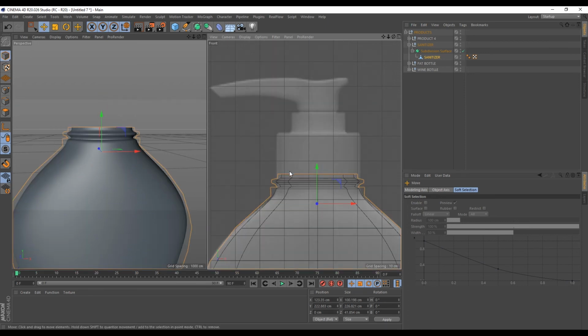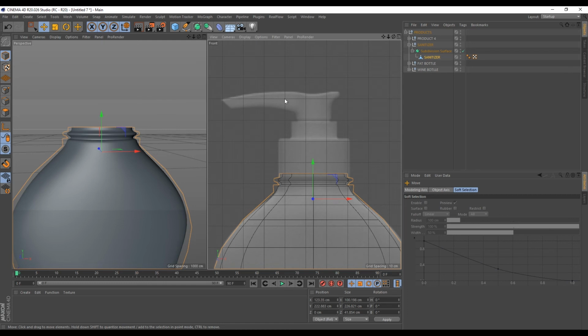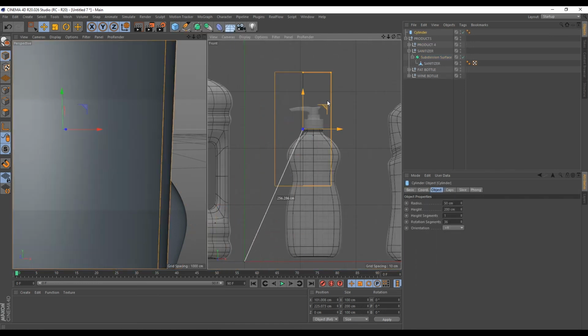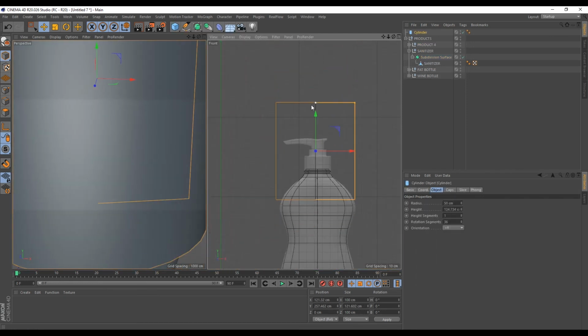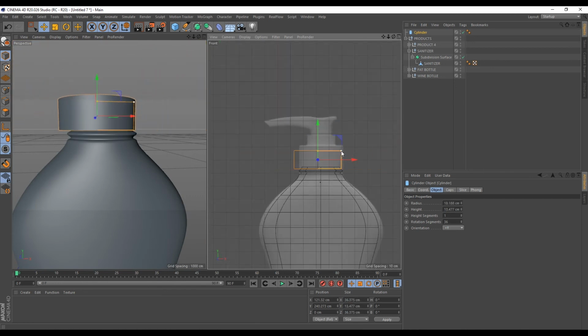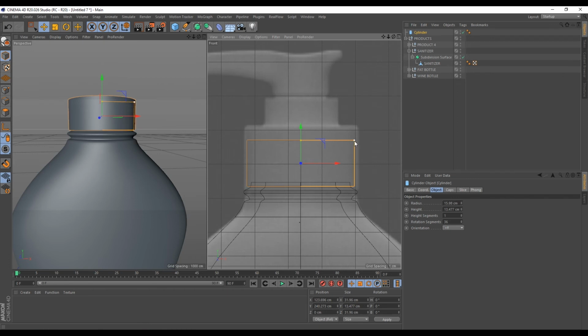So now let's bring a cylinder in to create this cover. So we'll create these two objects separately. We can create both of them from the same mesh, but I'll create them separately in case you want to animate this later on. So let's get a cylinder. Then I'll place that cylinder in the right position here. Then for this, I can work with 12 segments since I just need perfect circles.